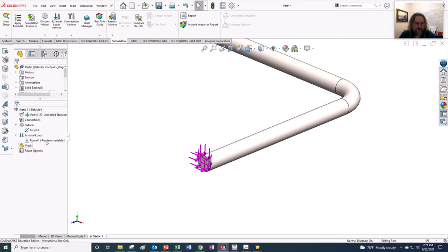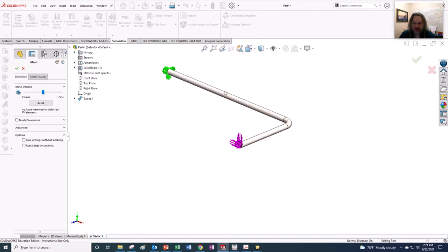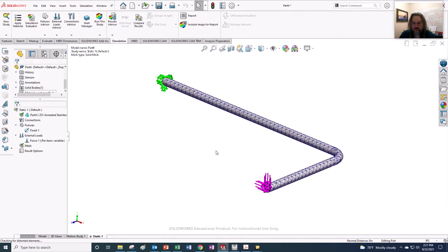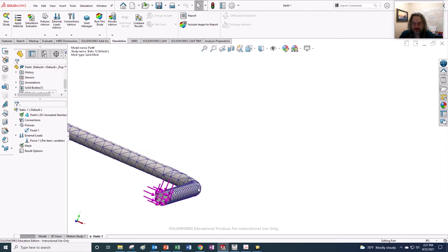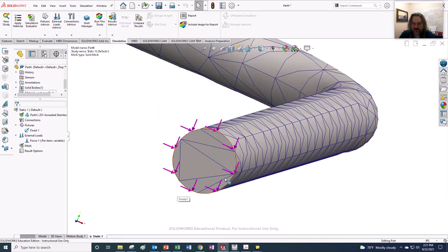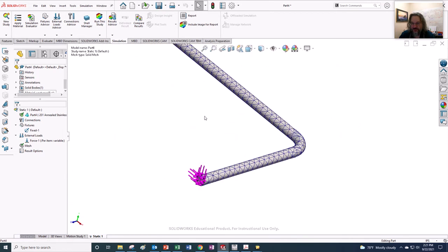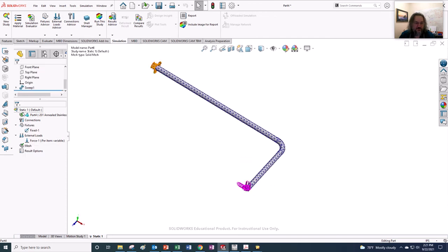And we're okay. Now let's hit the mesh, and let's actually make a crude mesh. Let's make as coarse a mesh as I can on this one and see what happens. All right, it wouldn't let me even make a rougher mesh than this. We kind of look and see. That looks really weird. See, there's a little skew going on there. That's definitely some weird looking elements. It's not looking pretty, but we'll see what happens anyway. We'll hit run. So we go up to the top.